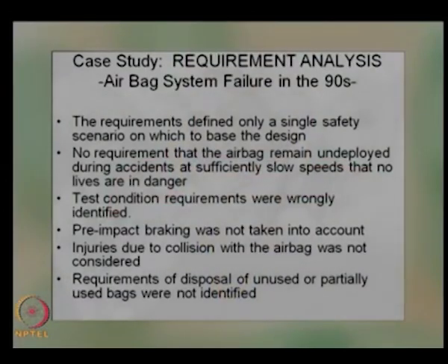So this pre-braking condition actually required the airbags to deploy well before the accident, or the time delay in deploying the airbag needed to be decided based on this pre-impact braking. That was not considered while designing the airbag. Similarly, injuries due to collision with the airbag were not considered.